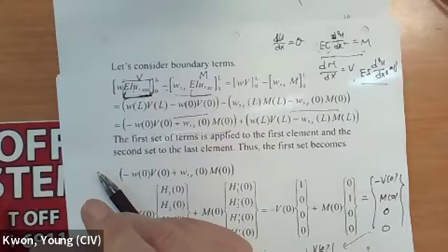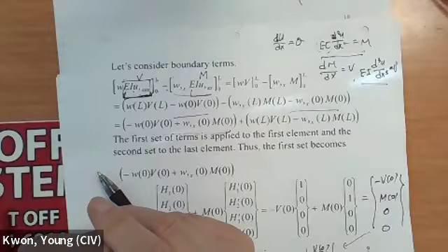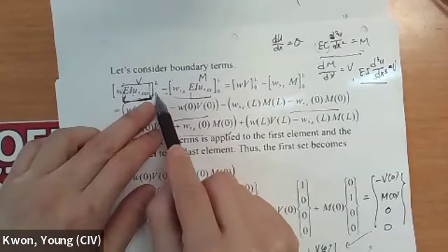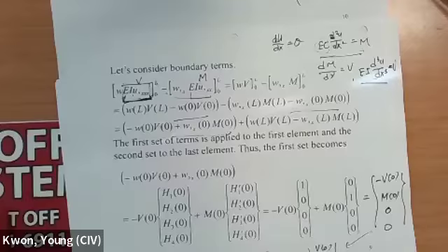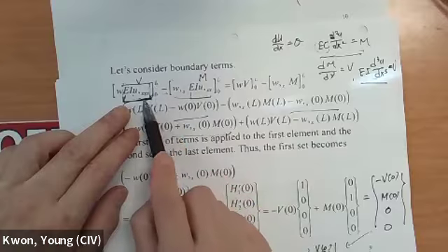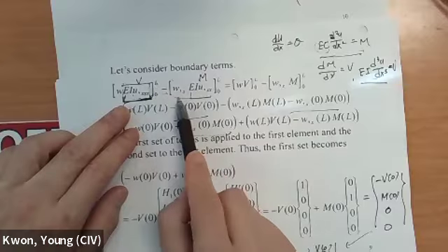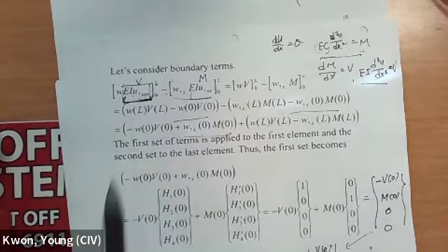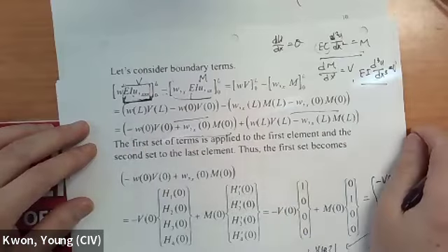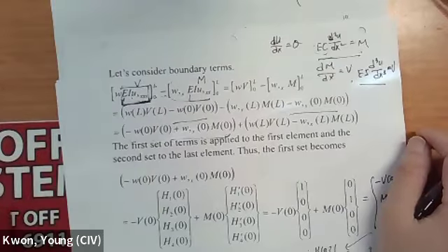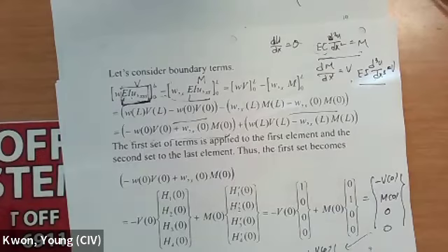So you're saying that this is just an evaluation of the whole thing for the shear force and an evaluation of the whole thing in terms of moment. This is evaluation at only two extreme boundary points, not along the length of the beam, right? This is the boundary integral. So evaluation at the right, evaluation at the left. This one-dimensional problem's boundary is going to be the point. So this is evaluated at a specific point of the right side or left side of the boundary. That makes sense. Okay, any other question?